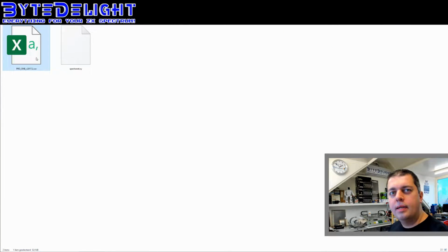One is from another interface, which is the DevMC Enjoy Pro 1. This is my source file because we have to get the Spectranet configuration file in exactly the same format. And I here have the XY file that Dylan Smith created with his software for pick and place machines, but that has to be translated to the format that my pick and place machine needs. So we're going to compare those file formats, and we're going to see how much trouble it will be to get it to the correct format.